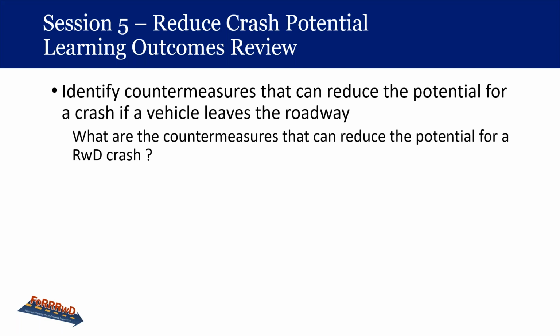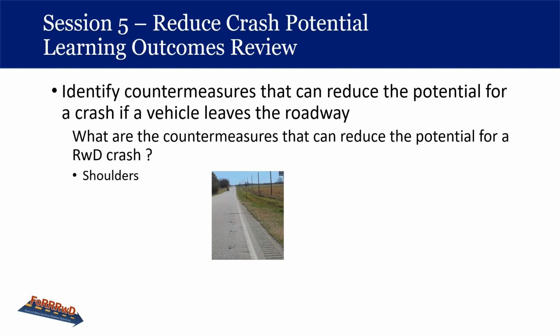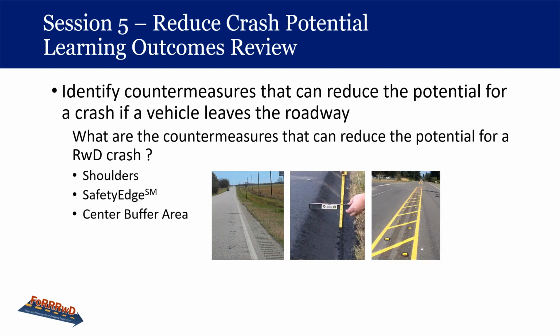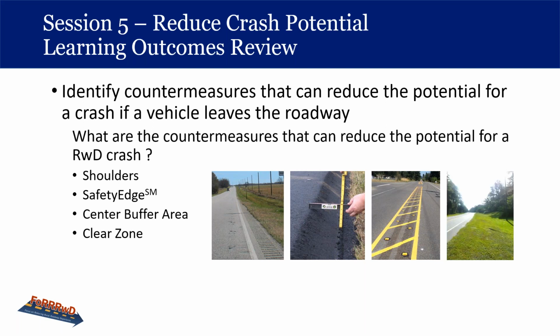All right, that's very good. They had widening shoulders, safety edge, center buffer area. I know I got a comment after the last class that this is a luxury that most agencies don't have. I agree with that. But you know, some of our roads might be capable of installing this improvement. And of course, working on a good clear zone alongside the roadway and traversable slopes. So those are our different countermeasures for helping to reduce the crash potential.